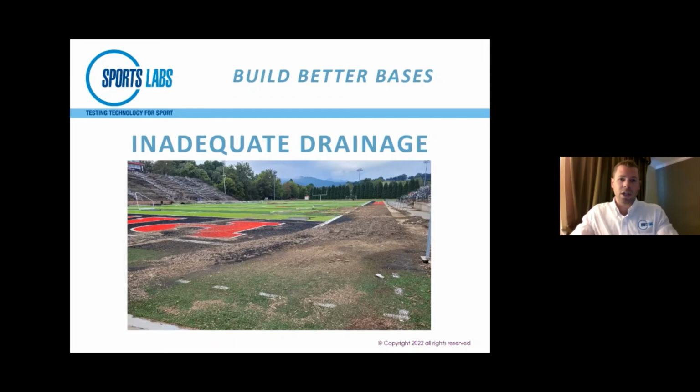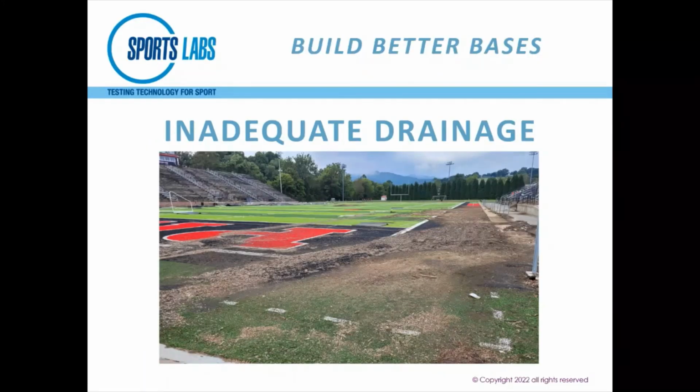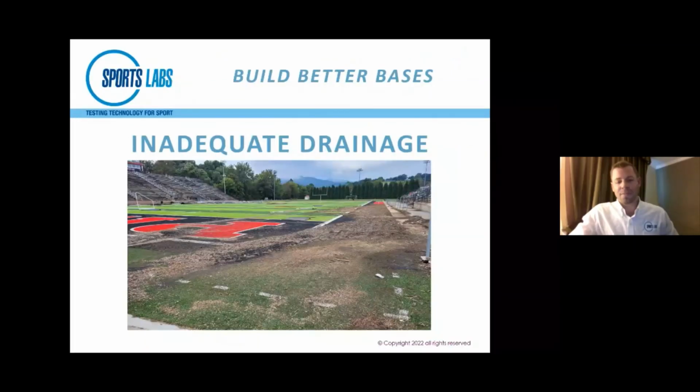Yeah, and I think it's very, very difficult to design for storms. Nowadays, I think the designers are looking at a 200-year storm event, which is occurring every other year now. So you design for a once-in-200-years storm event, and it comes along next year and washes out your field. In this case, it'd be really difficult to design for that. But obviously, organic infill is much more mobile than some of the other infill materials.